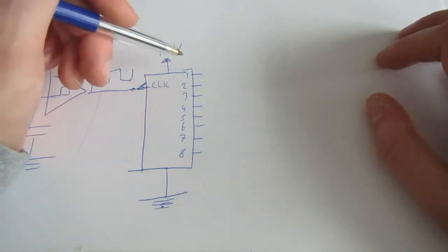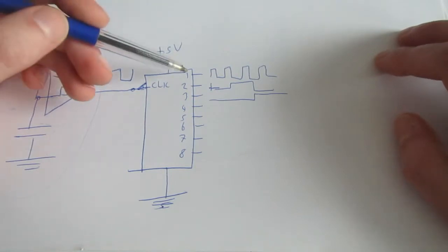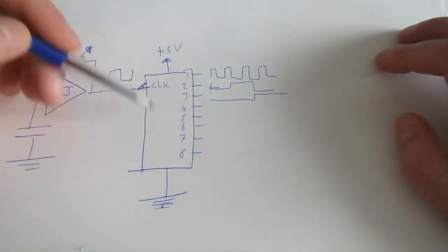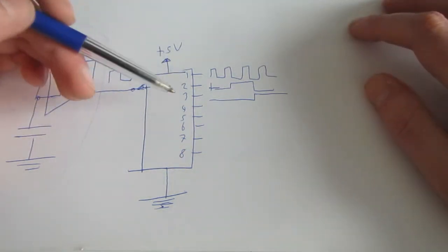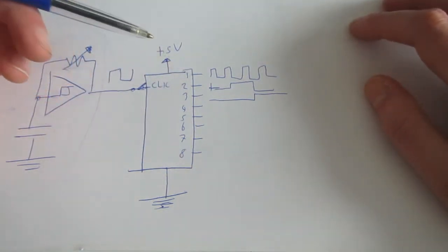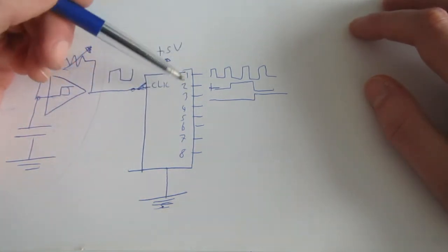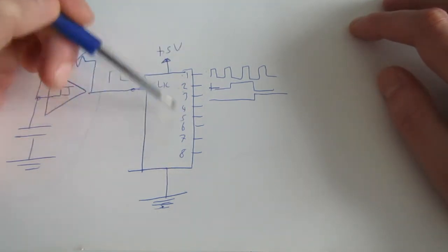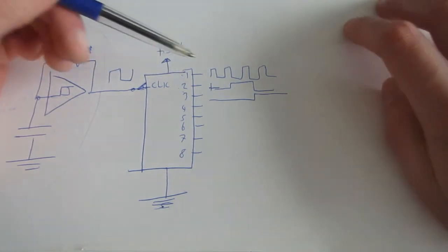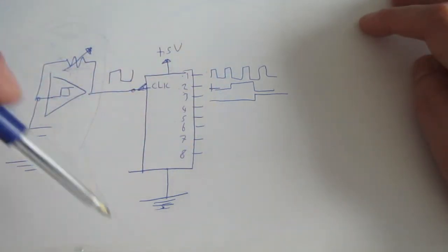Then the binary counter divides this down into octaves of square waves. Essentially what happens in a binary counter, for those who don't know, is it counts in binary from 0 to 255. This means if we look at this in the analog way, we essentially just see 8 octaves of square waves. Of course, the 8th is the lowest octave and the 1st is the highest octave. So essentially what we have here is an analog square wave oscillator and an analog frequency divider.